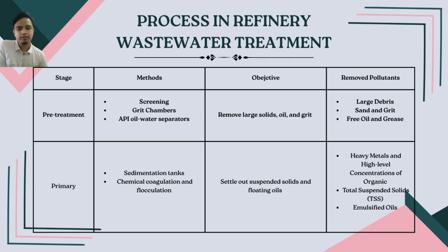Next, the primary stage. The methods are sedimentation tanks and chemical coagulation and flocculation. The objective is to settle out suspended solids and floating oils. The removed pollutants are heavy metals and high concentrations of organics. Next, total suspended solids, TSS, and the last one is emulsified oils.